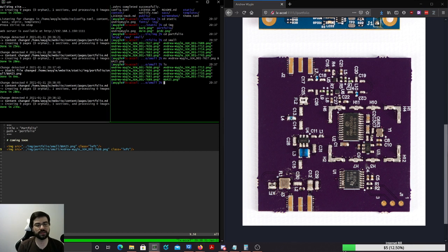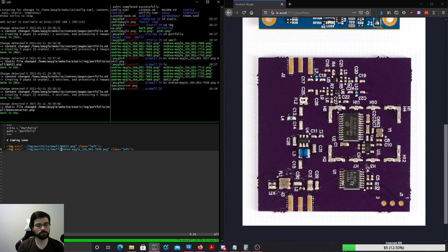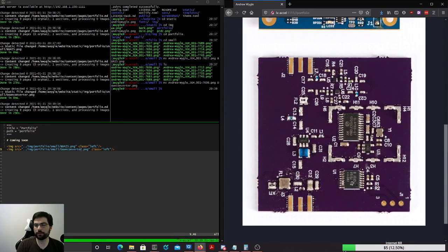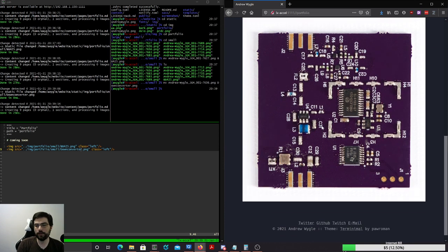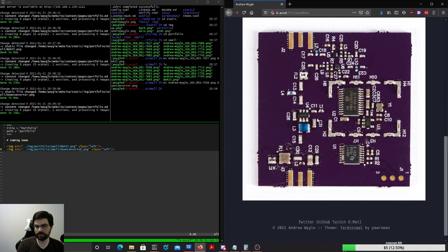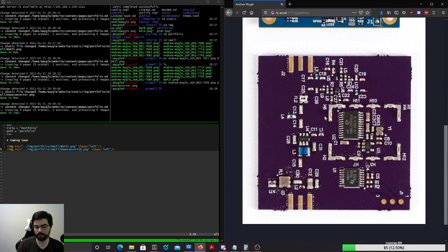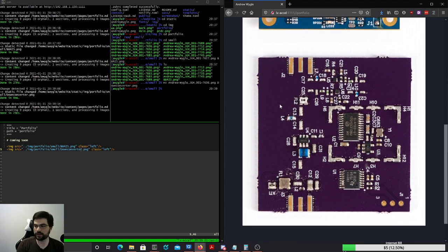All right, so that's what this is. This is 7636. So this is the down converter. This is a down converter that I designed for a different radio that I worked on, but basically the goal was to extend that radio so that it could support the 2100 megahertz band for receive. That's a pretty common band for CubeSats and stuff. The power target for this is under 100 milliwatts, and it did actually work, which is nice.